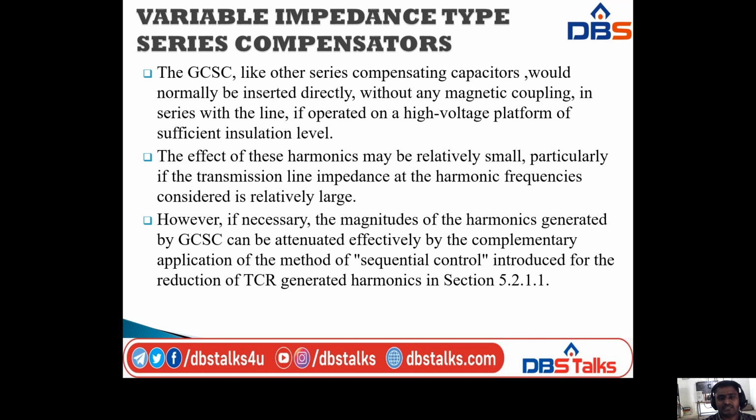Next, the GCSC, like other series compensating capacitors, would normally be inserted directly without any magnetic coupling, in series with the line. If operated on a high voltage platform of sufficient insulation level, the effect of these harmonics may be relatively small, particularly if the transmission line impedance at the harmonic frequency is relatively large.